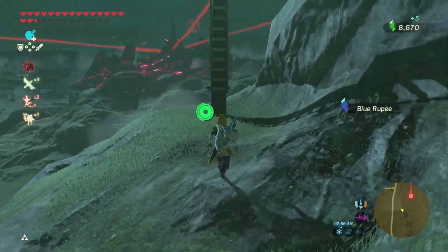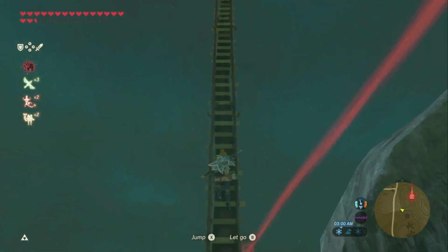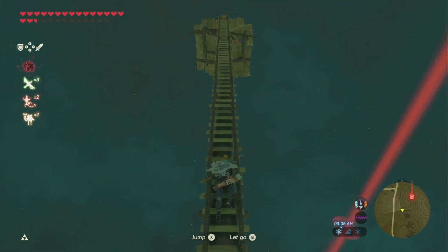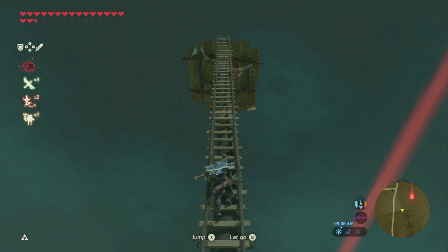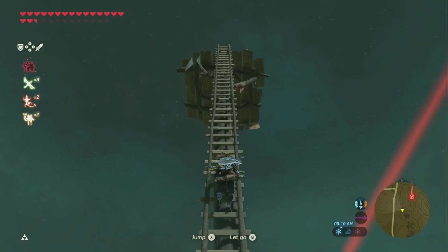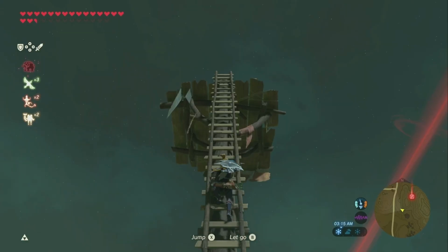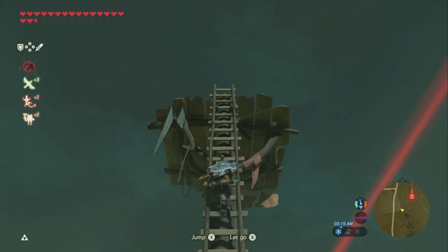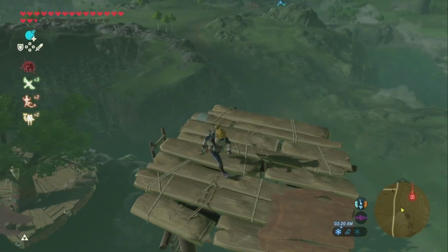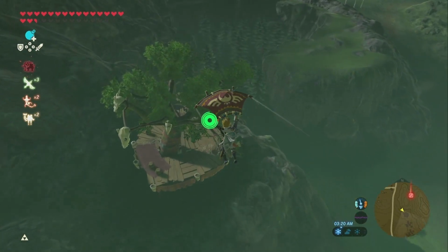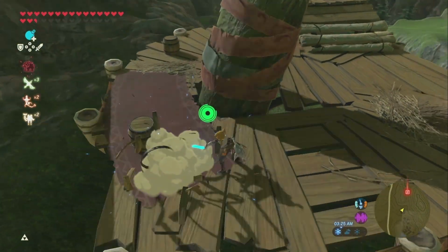The PEX design guide says the tubing can be connected directly to electric water heaters if the code and manufacturer's instructions allow. The guide says the tubing must be at least 6 inches away from the water heater exhaust vents. The guide also says manifold should be at least 36 inches above or 18 inches horizontally from the water heater.